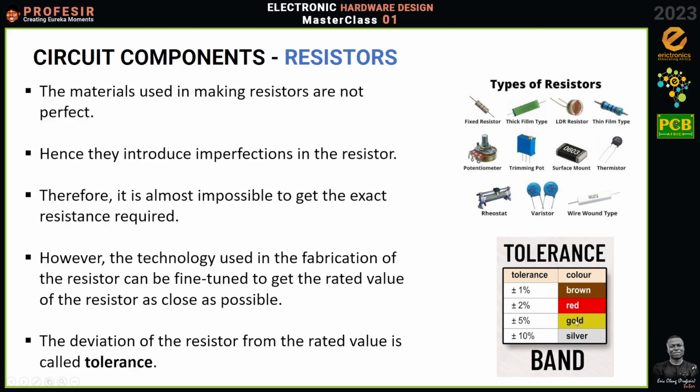these things are important if you are dealing with high precision work, like you are building military equipment, you are building hospital equipment, you are dealing with instrumentation and you need a lot of accuracy. Then you cannot be using low tolerance resistance values. You need very high tolerance, and high tolerance means it should have a very low percentage. Is that okay? So this is a good choice. If you don't have it, consider this. If you don't have it, consider that. This is a bad choice.